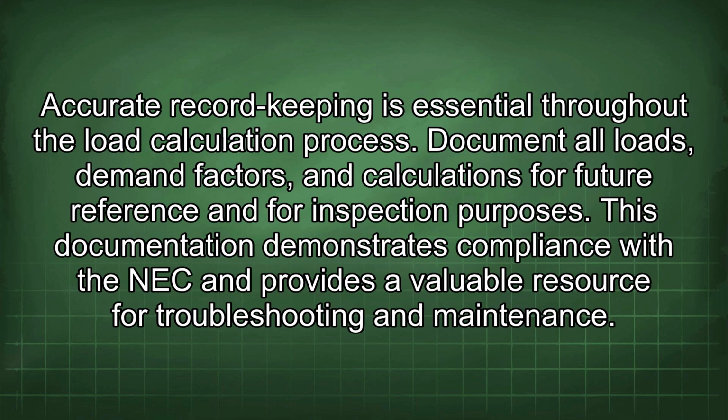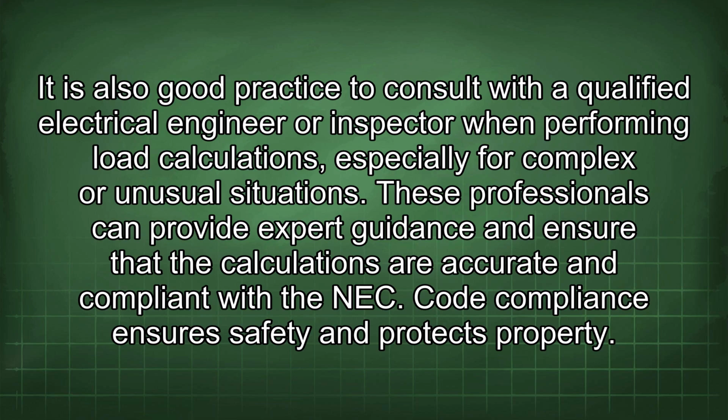Accurate record keeping is essential throughout the load calculation process. Document all loads, demand factors, and calculations for future reference and for inspection purposes. This documentation demonstrates compliance with the NEC and provides a valuable resource for troubleshooting and maintenance. It is also good practice to consult with a qualified electrical engineer or inspector when performing load calculations, especially for complex or unusual situations.